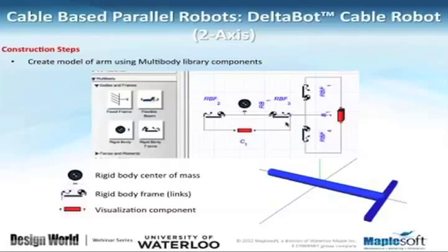And again, for that one, Maplesoft allows you to bring in mass, rigid body, and then after that you can bring in a rigid body frame, which is in fact links. So it generates this point, the one. So what you see here, that's the mass of the link. These two points, that point and this point on the right-hand side, are the start and the end of the arm. And again, the other two that you see here are rigid body frames or links that are showing the end points of this arm. So it's very easy to make this.